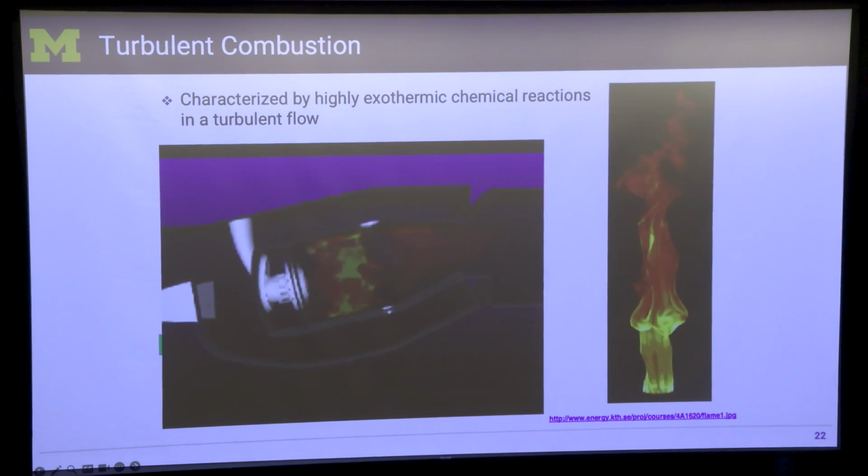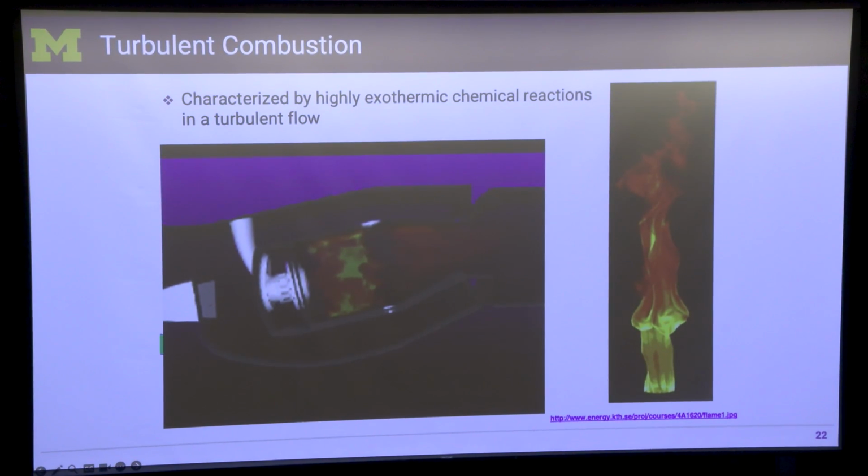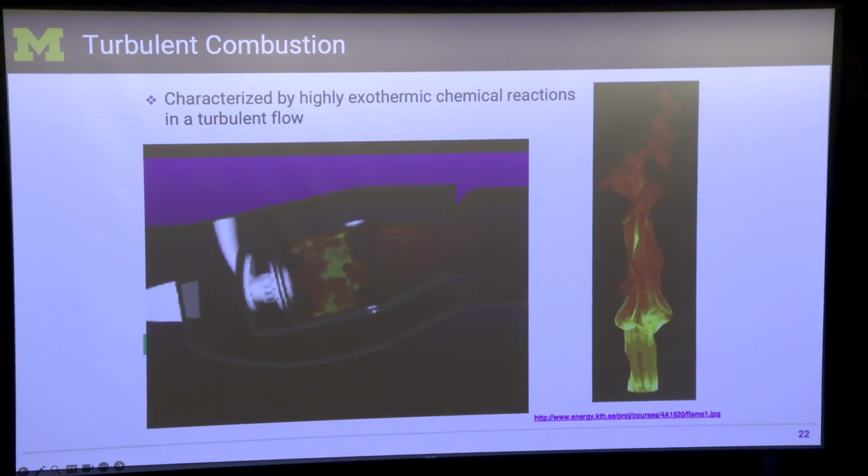And on the right-hand side is a lower Reynolds number flame similar to that. Now, if you have seen laminar flames, like a candle, right? Compared to that, these flames are complex only because they have these intermittent structures. Turbulence tries to change the flame shape. It contorts it, right? So it's like it's pulling it in different directions.